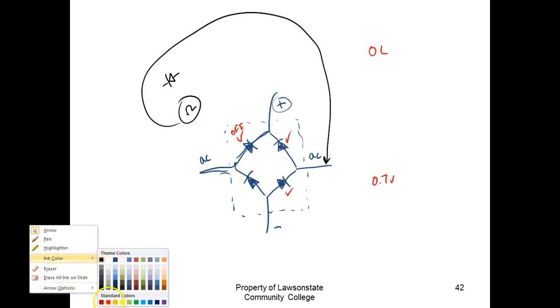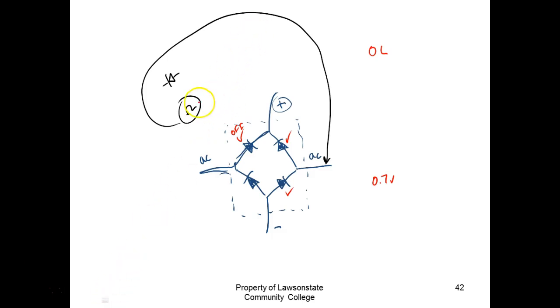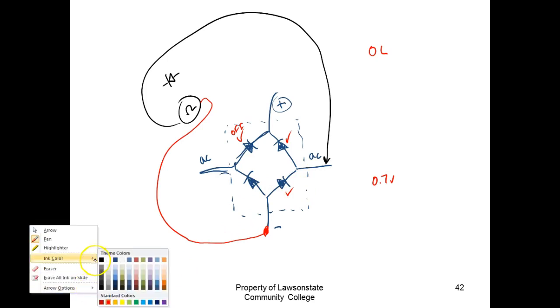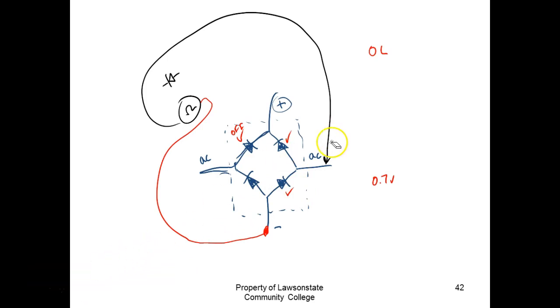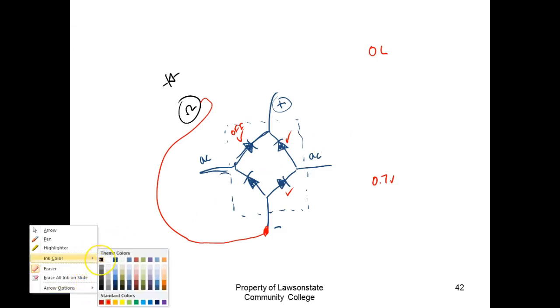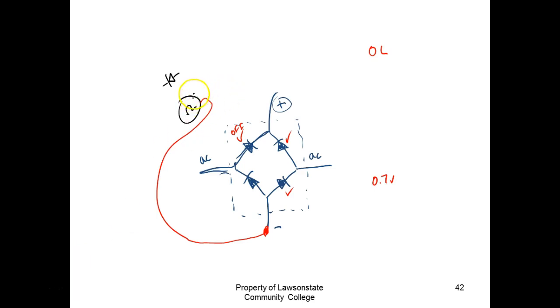I think I need to calibrate my pins. Did I move this? Okay. So what we would do is we would clamp this on, right? And then what do I do? So what we did, we just checked that one. What would I do now? I'll take this one and move it over to the other AC side. And now we're checking which one. And then I would reverse my leads and check for reverse bias, right?